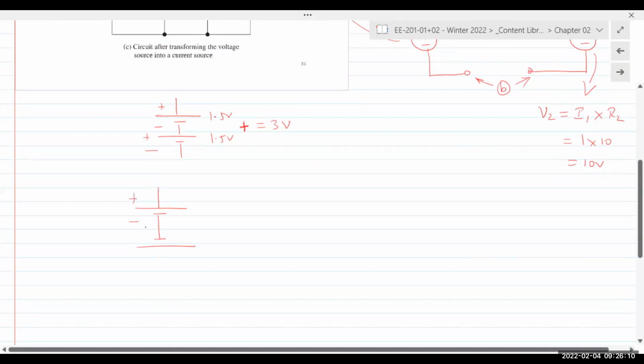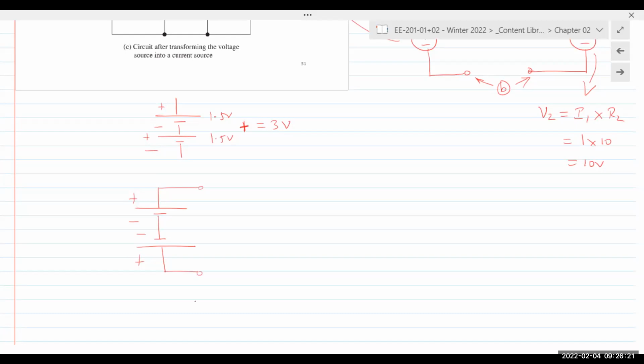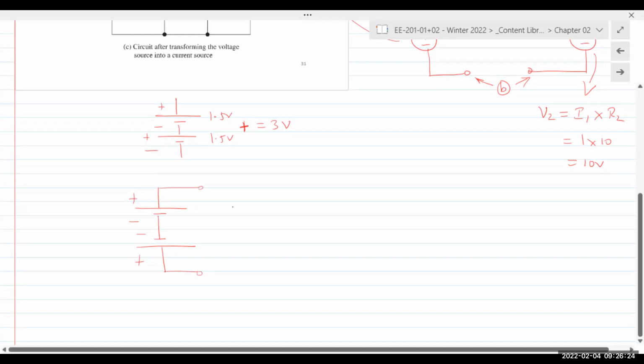and I connect a plus and a minus and a minus and a plus, and I try to find the output voltage here, if both of them are 1.5 volts each, what do you get? You get 0, right? So if this is 1.5 volts and this is 1.5 volts, you would subtract and you would get 0 volts. If this is a 3-volt cell and this is a 1.5 volt cell, you'll get 3 minus 1.5, 1.5 volts, because they're opposing each other.